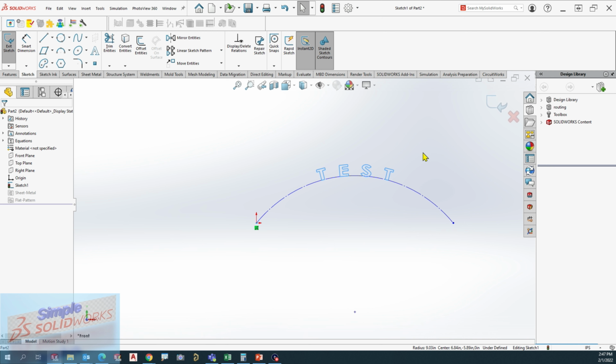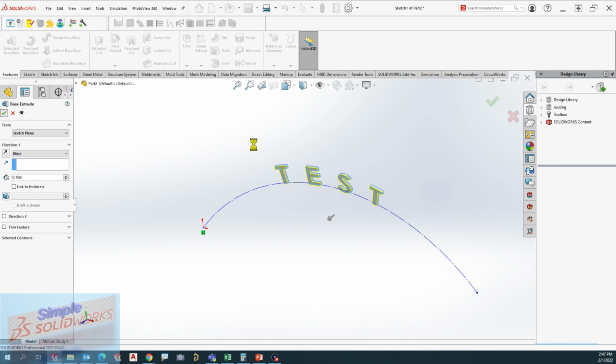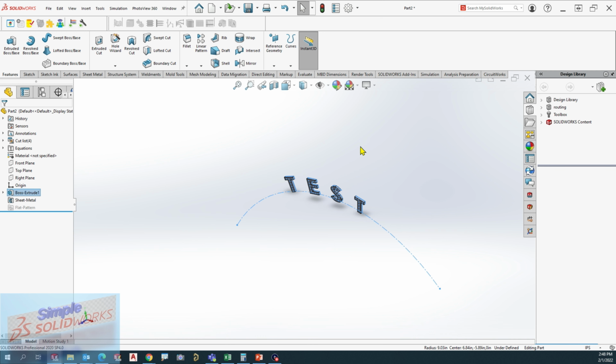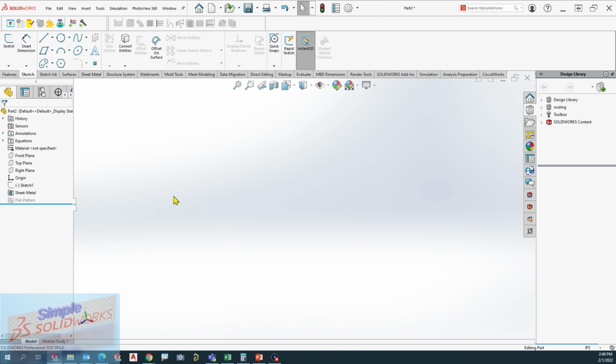So that in itself, you can then come back. If you were to put this on as a feature, you can say, well, I want to extrude it. So it picks it, and you say, yeah. Boom. Now I got a test. I got the text in there on the face of my product. You can either deboss it or emboss it: extrude inward to cut it out, or extrude out to make it on top of the first surface itself. So that's a pretty useful thing to have. I like to use that a lot, to identify things if I want something to be lasered onto my part.